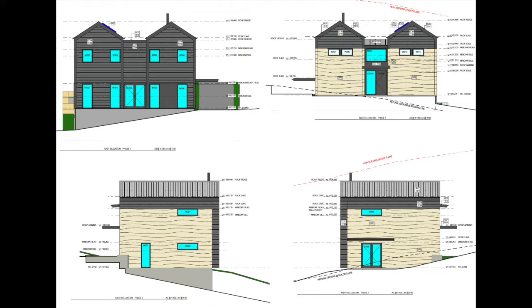An external elevation or external elevations are also required as part of the DA, and that's explaining the relationship as viewed from the outside of the face of the building. The technical term for this is an orthographic view, and basically that means it's a flat view. So it's not what we'd see with our eye, which would be a perspective, but it's a flat view viewed from the front, the sides, and the back, explaining what the exterior face of that house would look like. Now, depending on the council requirements, that may need to be coloured.